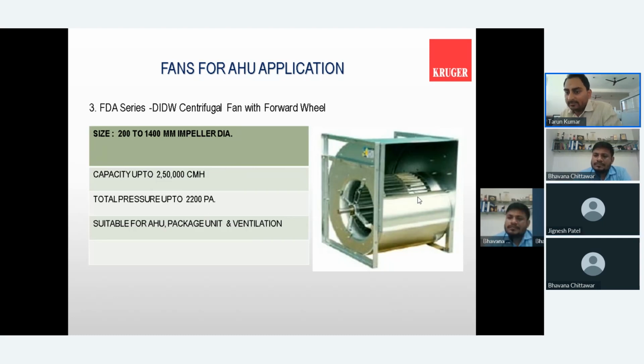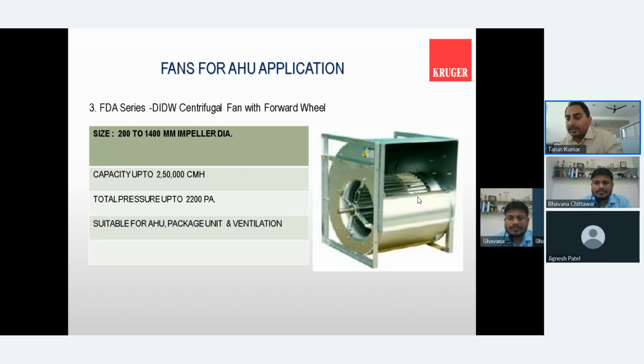Yes sir. Whenever we take the GAD approval, we always confirm from the system, from the contractor, what exact direction is required, like if their duct rotation is on some other side, then we have to go with counterclockwise. That depends completely on the duct routing.